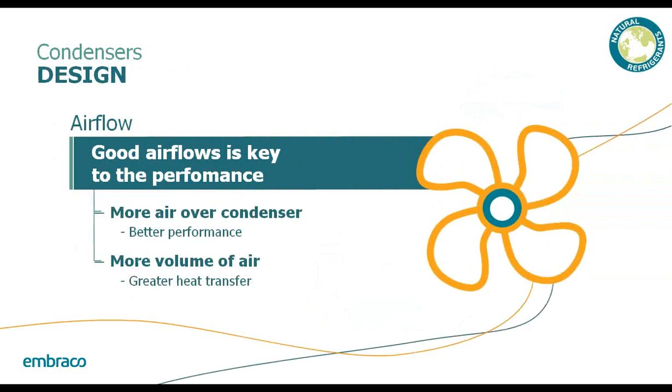As with the evaporator, airflow is again key to performance. The more air you're able to move over your condenser, the better the performance of your system. Again, consider a higher velocity airflow with a larger fan or a faster fan speed if possible. Take a look at CFD modeling if you have the capability, as with the evaporator.